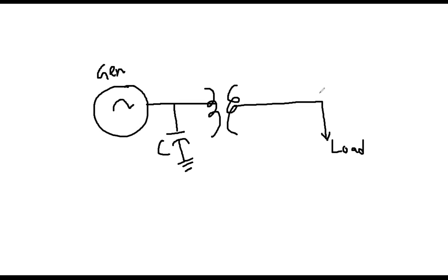So, and then the load voltage was given, probably 1280 volt RMS, whatever it is. And it also says the load side has 2 times the winding than the generator side. This means if you say this side is 1, then this side is 2. This means the load side has 2 times the number of turns as compared to the generator side.